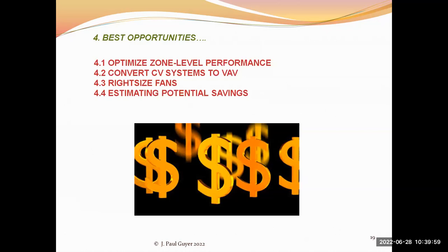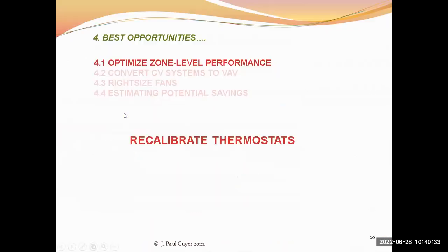And these things can result in an older building where the fan is too big for its operating environment today. And so if you can reduce the size of the fan, that reduces the power consumed at the fan. So right sizing the fans is an important opportunity.